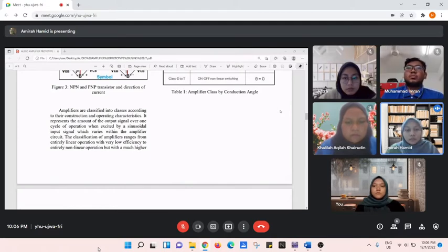The second amplifier classes are D, E, F, G, S, and T, and so on, which use digital circuits and pulse width modulation, PWM, to constantly switch the signal between full on and full off, driving the output hard into the transistor saturation and cut-off region.